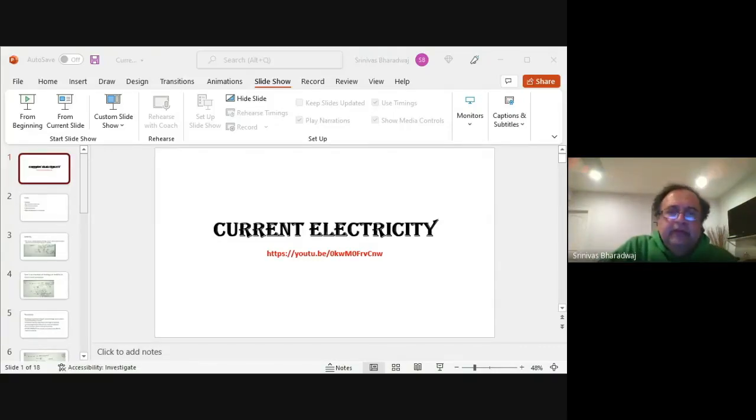So in this case, if you see blue, blue is 6. Red is 2. So 62, right? Or is this pink? Violet? Whatever it is. So if it is red, it is 62, right? So 62 into 10 to the power of 0. If it is black, 62 into 10 to the power of 0 is just 62, right?